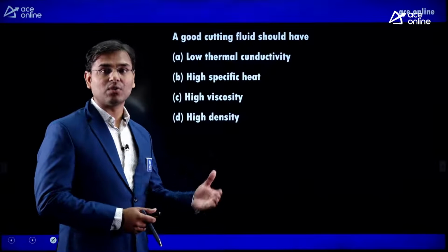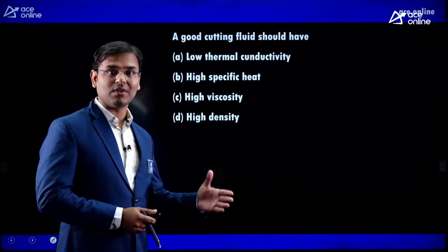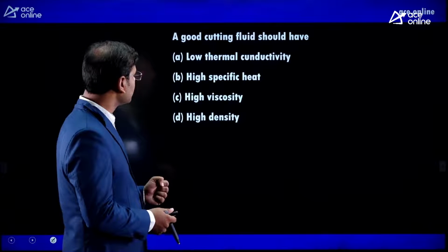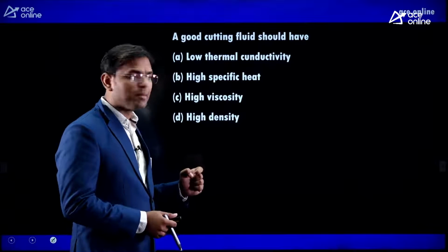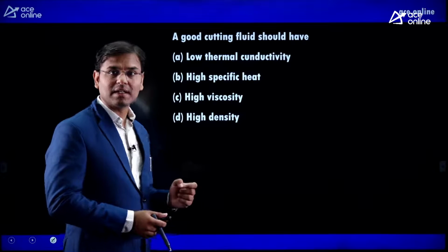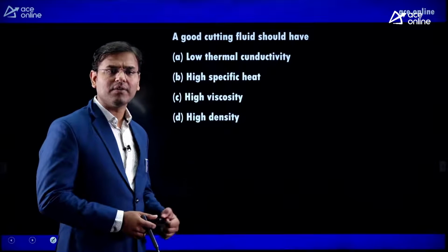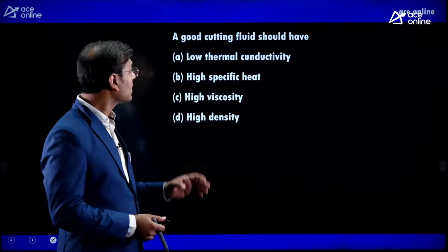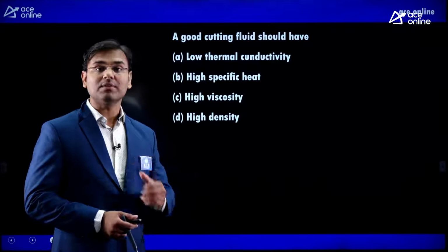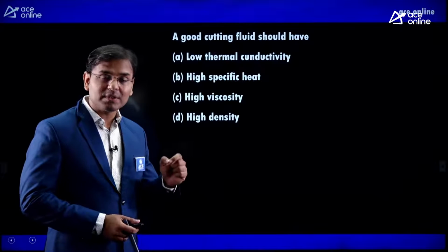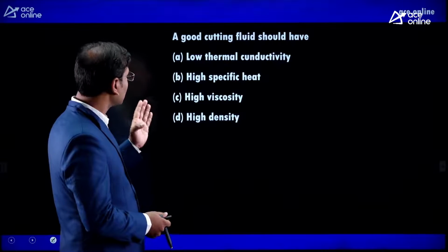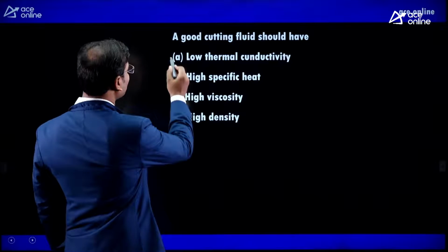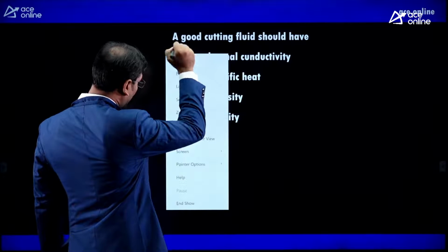There are two types of cutting fluid, coolant and lubricant. The cutting fluid we use must have high thermal conductivity, because it needs to carry away the heat from the machining environment. But here the option is low thermal conductivity, which is wrong.